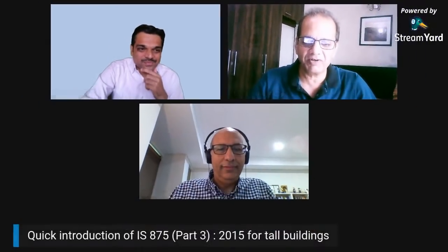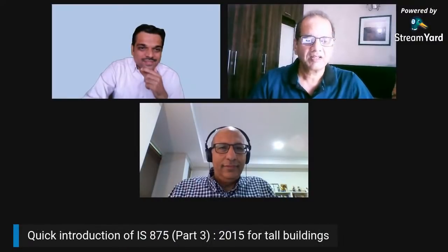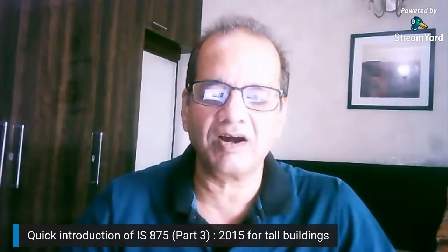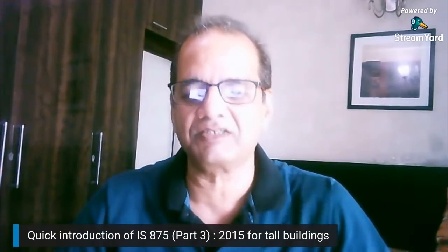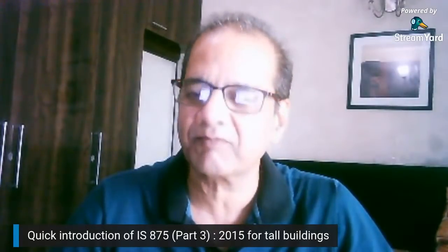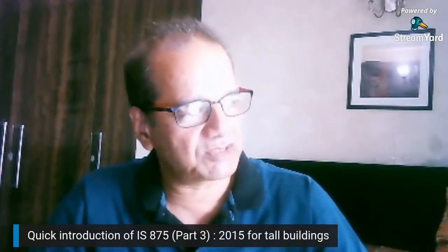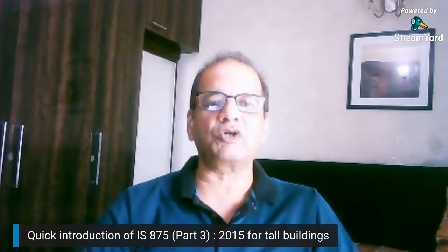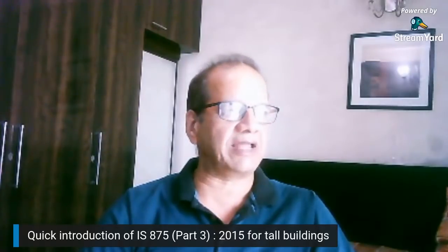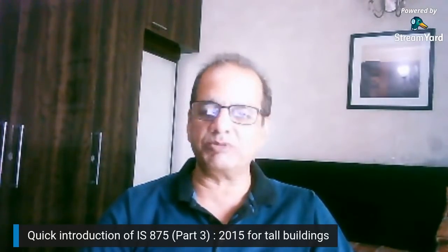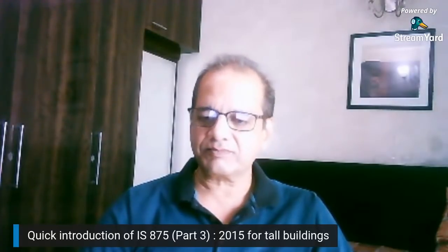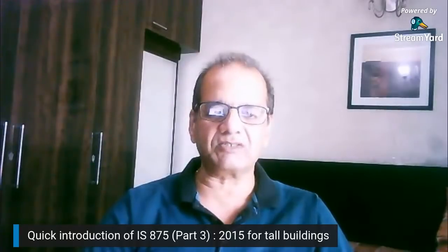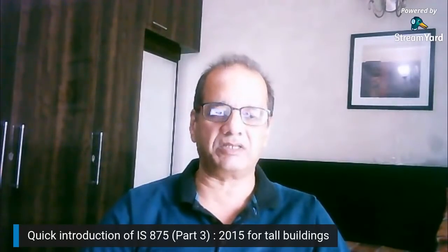Good morning, all my dear friends who are joining this session and are keen to know more about the wind forces on tall buildings. Every structure which comes in the way of the wind attracts or generates wind pressure and wind force in turn. We have discussed low-rise buildings in the last session. Today we are going to talk about tall buildings. Though every other structure, like lattice towers, chimneys, bridges, or anything else, attracts wind, we are focusing today on tall buildings and our code, IS 875 Part 3.